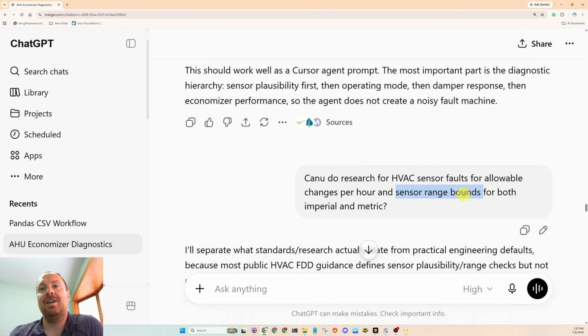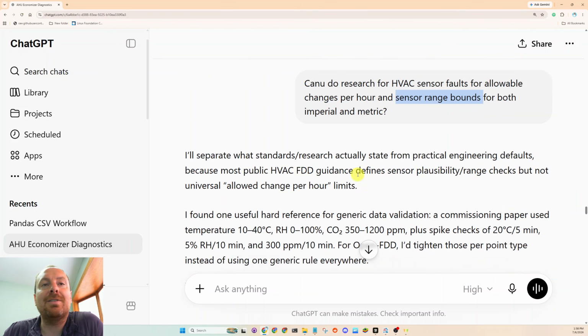If you wanted to score how well a maintenance team monitors these HVAC systems, immediately, if they tend to the alarm console, that's a very high indication that they're a really good maintenance team. That's just my opinion. If they're tending to the alarm console, they're more than likely tending to belts and filters in the HVAC system. They're probably not monkeying with set points. They shouldn't be. So you have alarm consoles.